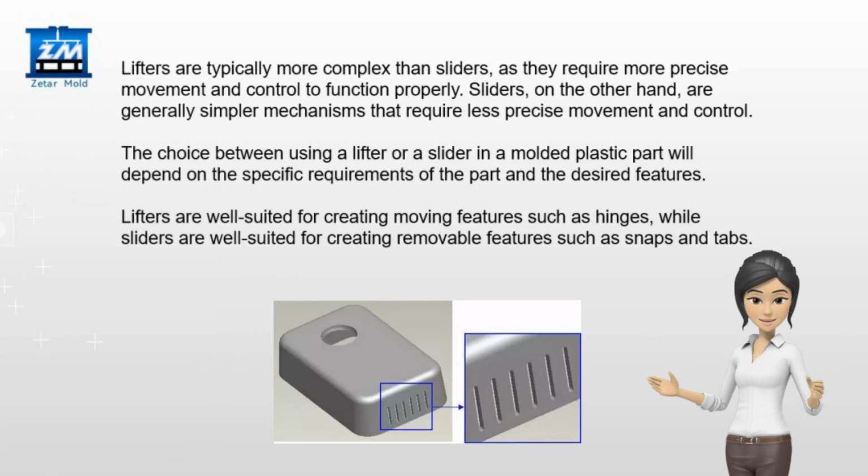The choice between using a lifter or a slider in a molded plastic part will depend on the specific requirements of the part and the desired features. Lifters are well suited for creating moving features such as hinges, while sliders are well suited for creating removable features such as snaps and tabs.